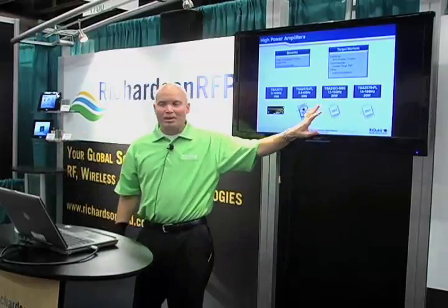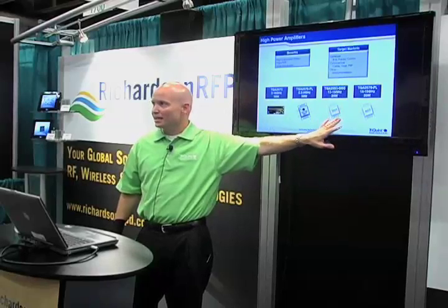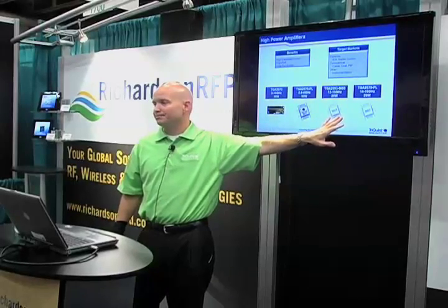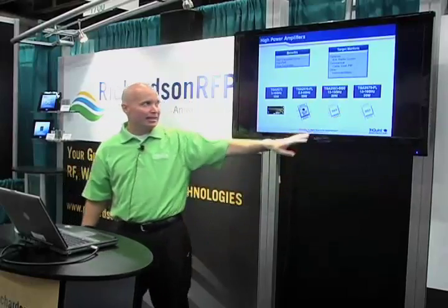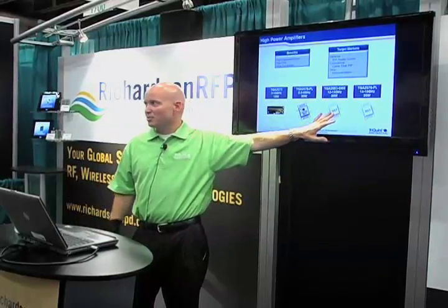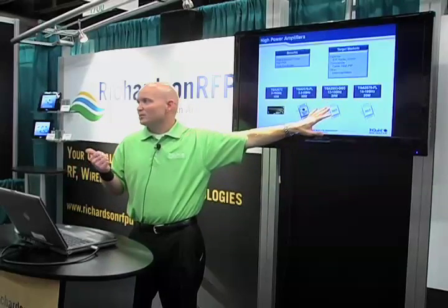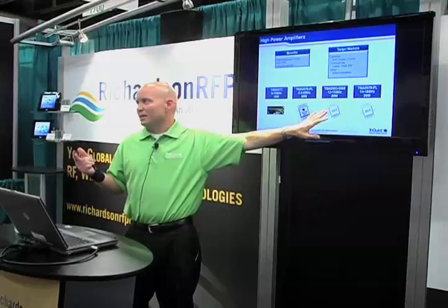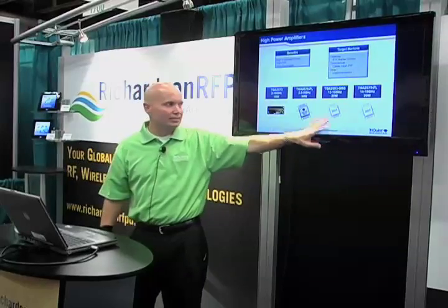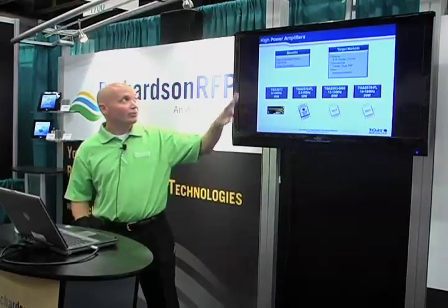What we were able to achieve with gallium arsenide is nowhere near what we can achieve with GaN at these frequencies that I'm showing here. So again, these are 20 watt levels, achieving efficiencies of 25 to 30%, where with gallium arsenide you're looking at a 6 watt level with efficiencies around 15 or 20%. So really a step function improvement in performance using gallium nitride with the power amplifier.